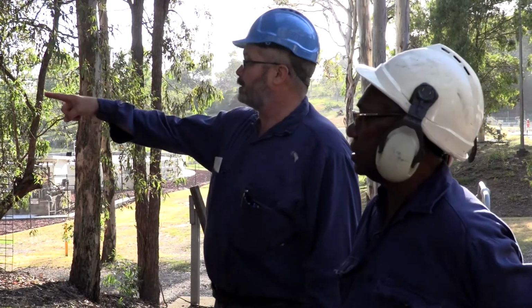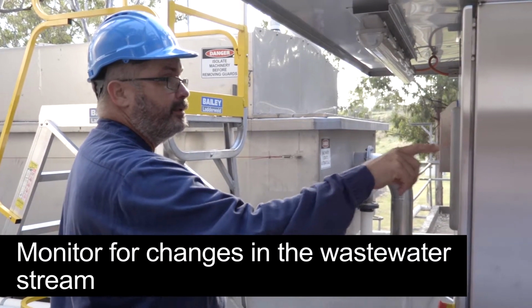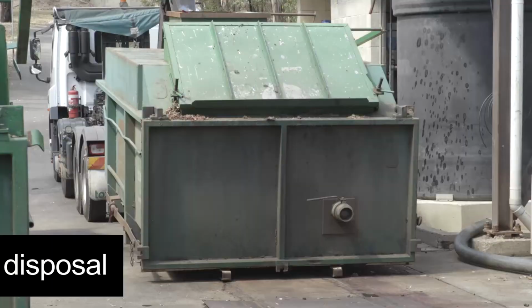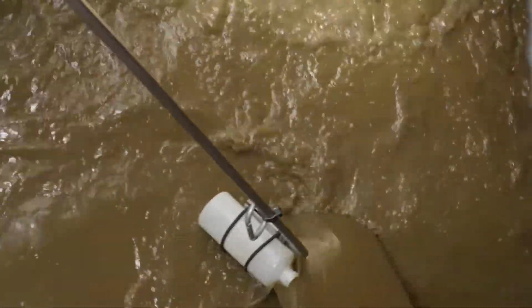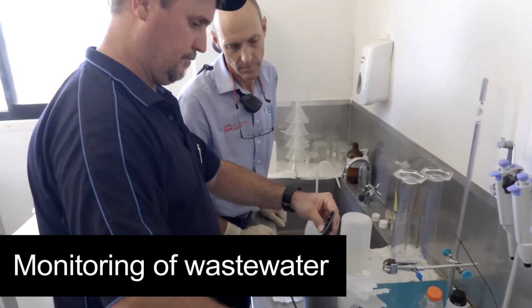Supervisors should monitor the upstream treatment area for evidence of large amounts of blood or tallow. This may indicate that valuable product has been lost down the drain. They should also oversee the proper disposal of waste solids from the upstream process area. Regular monitoring of discharge to sewer also needs to be conducted to meet discharge conditions and assess the operation of the treatment plant.